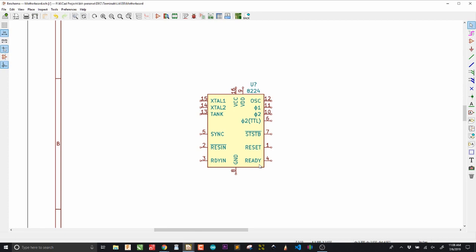One thing that you might find is an output that should actually be a tri-state. That means you can connect multiple outputs together, but only one chip on that line is going to be active at once. So instead of making it an output, you make it a tri-state, because that chip has to have some way of tri-stating its output so that other chips can output a signal.